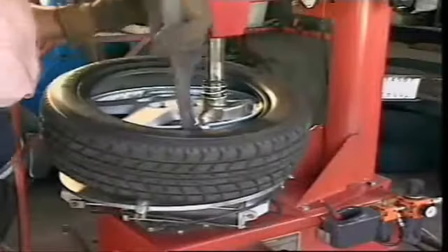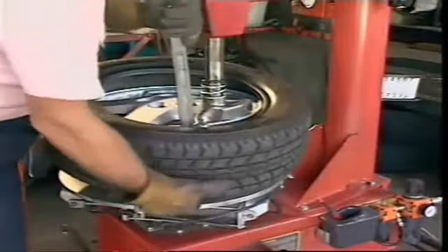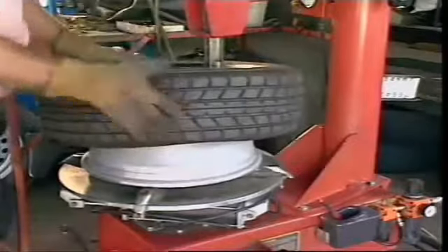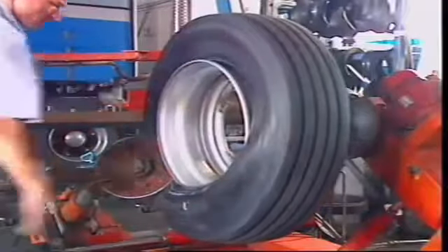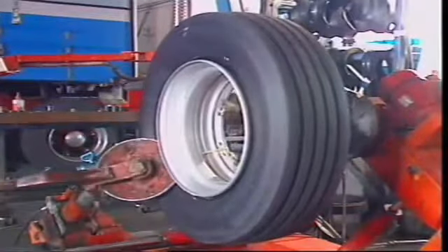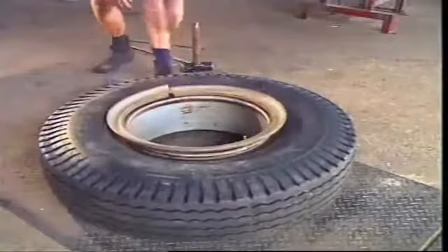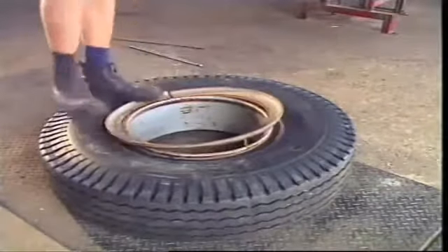Most passenger car wheels are of well or drop center design. This design allows for tyre removal and fitting. Tyres for heavy goods vehicles are much stiffer, but they can also be fitted to a well-based rim or to a flat-based detachable flange rim, depending on construction.